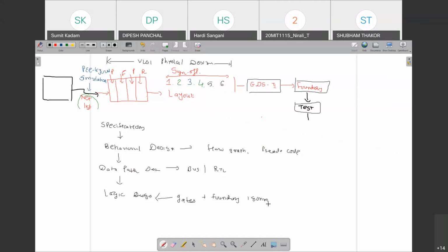But here in this ASIC design flow, application specific integrated circuits design flow, you have to add the foundry based on your design requirements. So once you add the foundry, all metals, metal weights, everything comes into that foundry file. So in the software, we have to add this file with the logic design, and then we get the accurate report: what is the speed, area, and power?